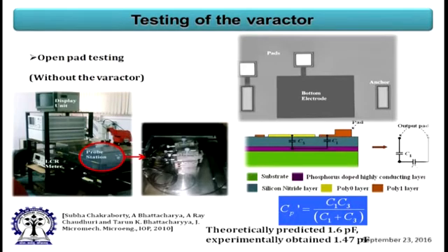If you look at that, theoretically predicted is 1.6 picofarad, and experimentally we got 1.47, which is only the test structure, that means without the device.